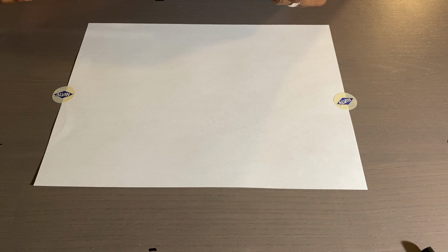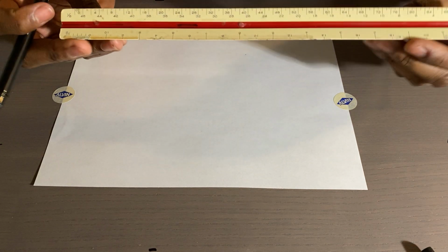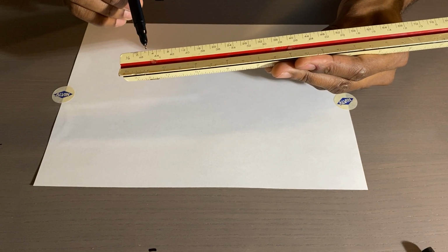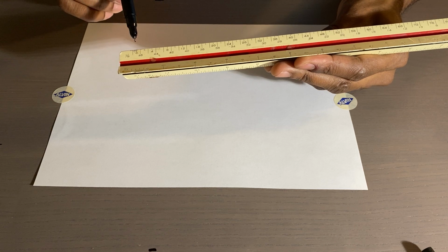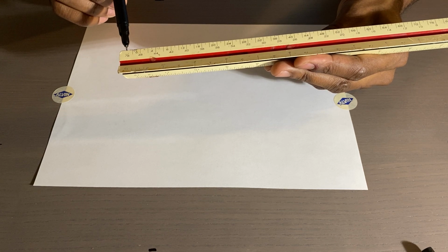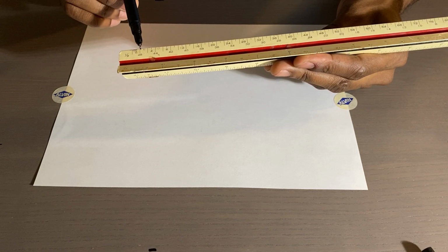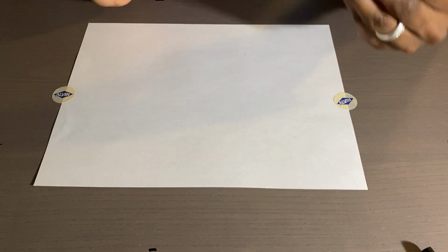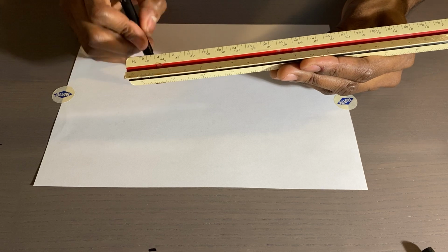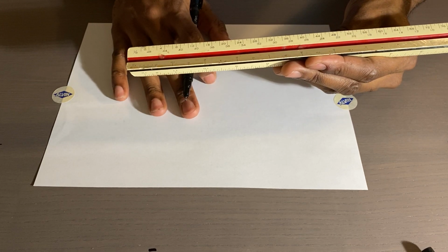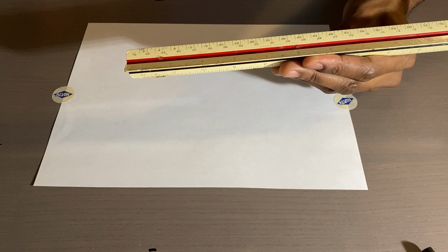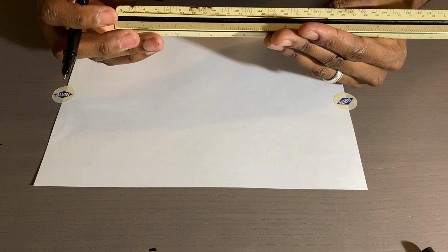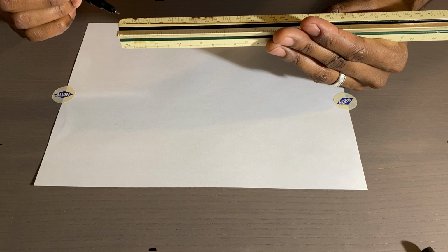So let me see if I can show you this. If you look at that, you'll see that says 1/8 of an inch, right? That means each of these are 1/8 increments, and this is 1/8 inch equals a foot. So each one of these 1/8 inch increments in real space on the ruler represents 1 foot on paper space. So that's what that means when we say there's an eighth of an inch to a foot. Same thing with this one here. This is 3/32.